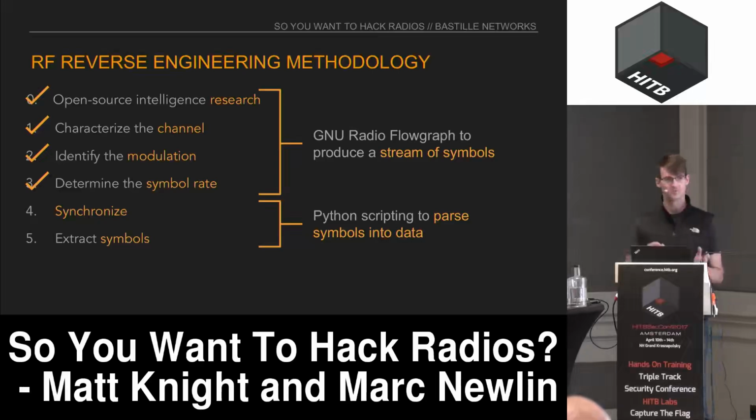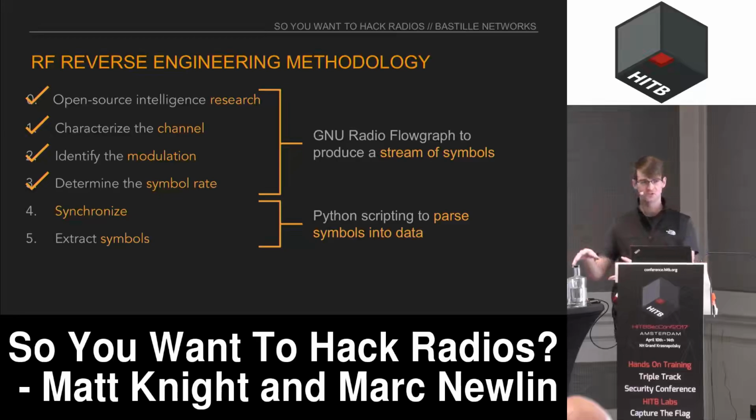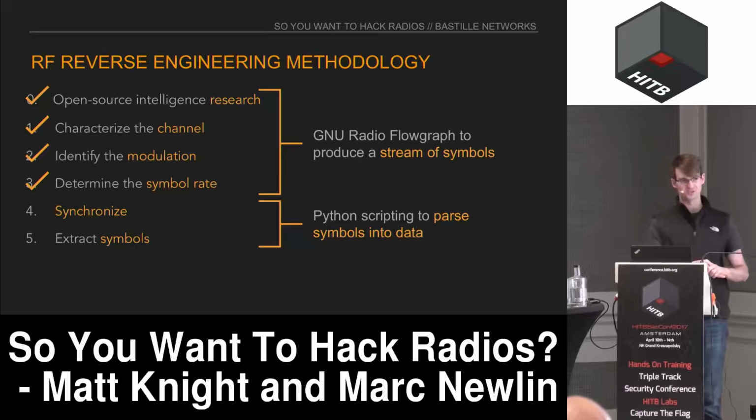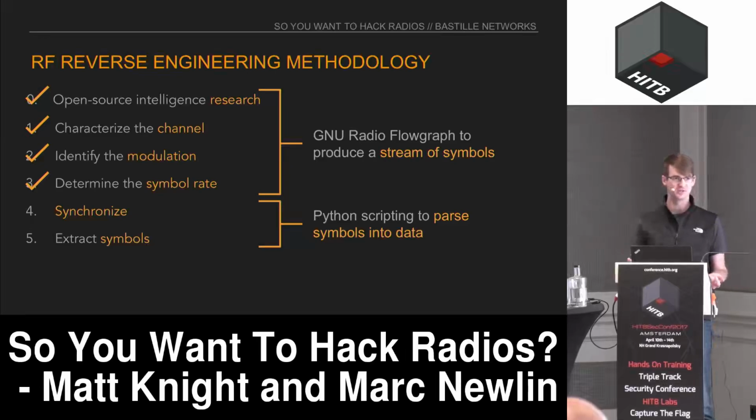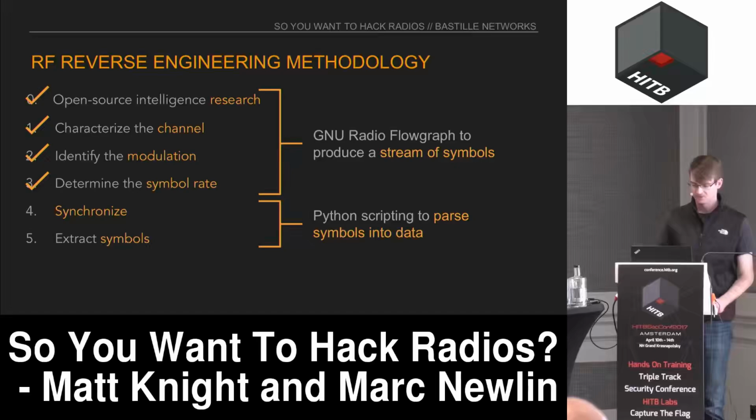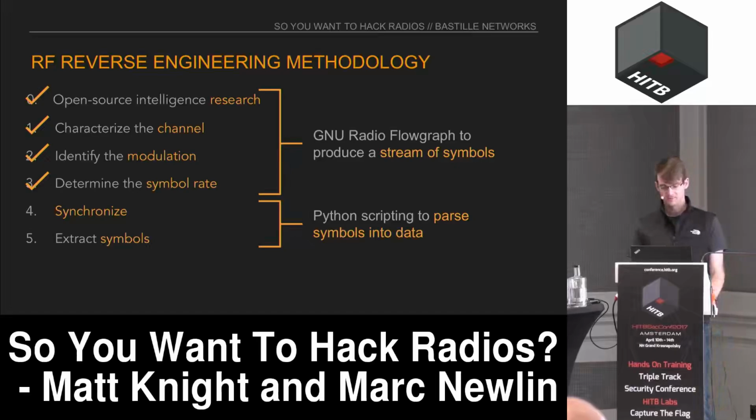Again, this flow graph that we're going to put together is essentially going to capture raw radio information using the SDR, do some math on it, and it's just going to give us a stream of 1s and 0s. Once we have the 1s and 0s on our system, on a disk, we can parse through them using any tools we desire, right? You can use any language, any workflow you want, because it's just a binary format, just like any other data. So we're going to implement that with Python, because Python's really easy.